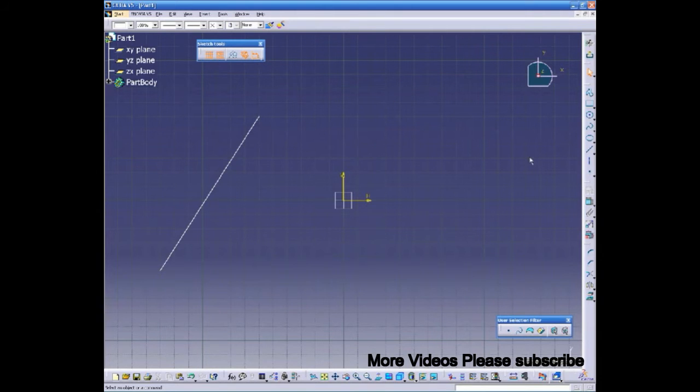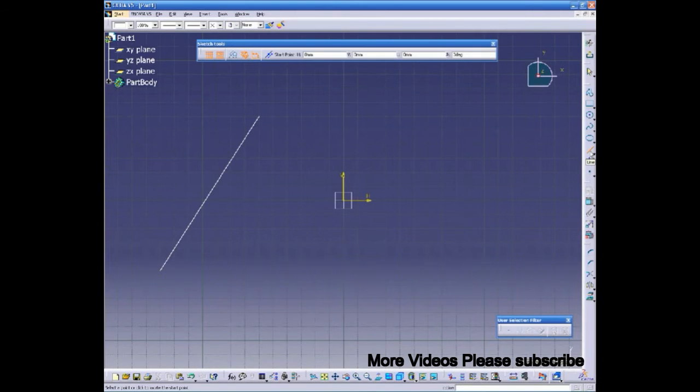Click the line icon. Right-click the first line and select Parameter. Then set as Angle Reference from the contextual menu. You see now, we have red arrow. It is indicating the orientation of the reference line. Type in the Sketcher Tools toolbar, in the angle field A equals 75 degrees, and press Enter.